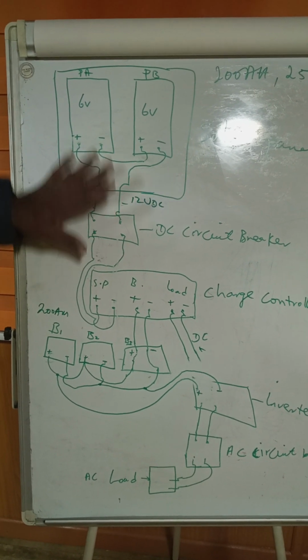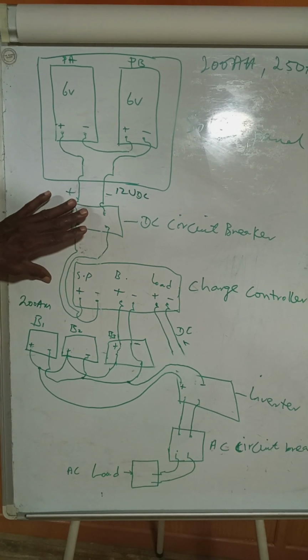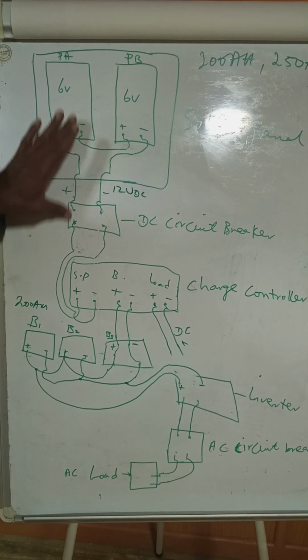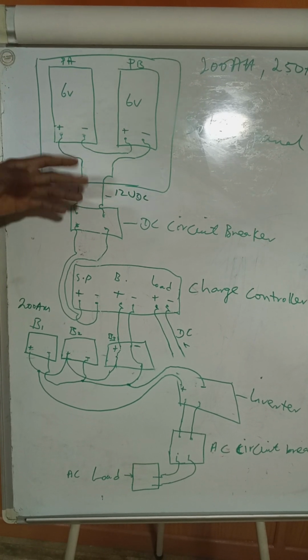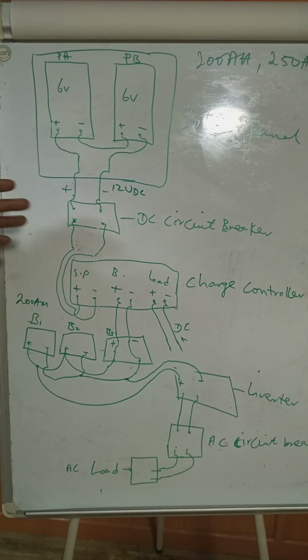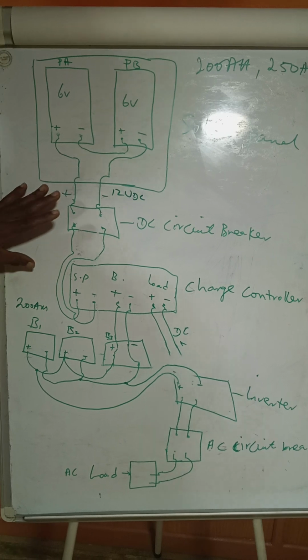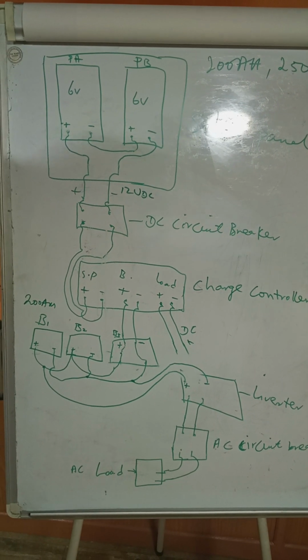It has to be sized according to your component. If the current you have here is not more than 20 amps, you can't bring a circuit breaker of 100 amps. It is a wrong design. Your system will not be effectively protected.